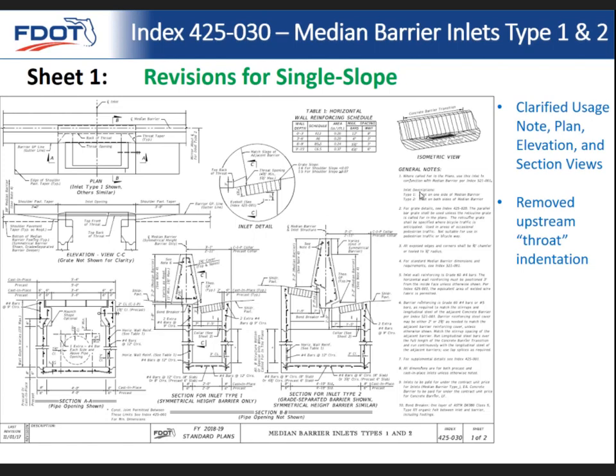We've removed the throat indentation. You can see on the isometric, it used to be up here, typically upstream when you have water flowing towards it. Speaking with Carl Spirio, the state drainage engineer, we've recognized that the benefit from that wasn't quite worth the time it took to construct these things. We found that in a lot of cases, contractors were just chiseling out a throat indentation here, and it wasn't really performing as we had intended.